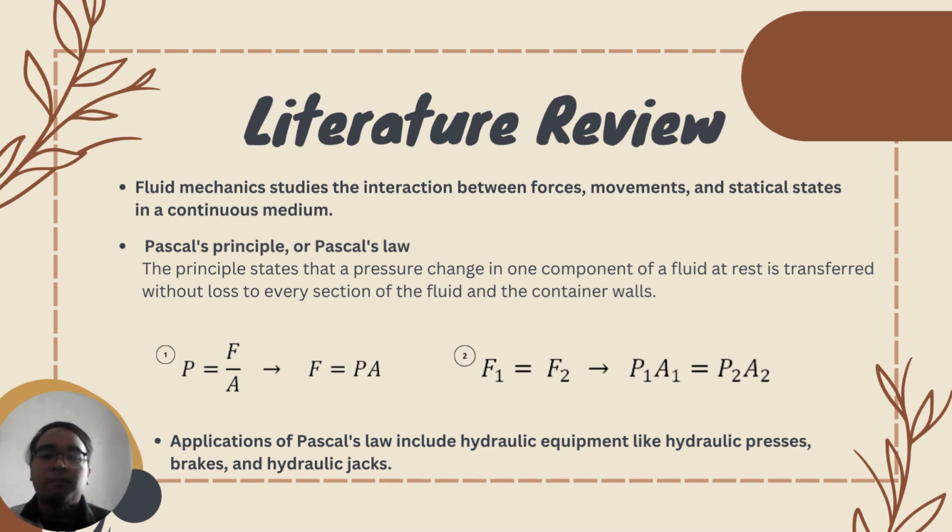The formula in Pascal's principle is P equals F over A, or F equals PA. For the force transferred with the same value, F1 equals F2, which means P1 A1 equals P2 A2. The application of Pascal's principle is usually in hydraulic equipment such as hydraulic press, brakes, and hydraulic jack.